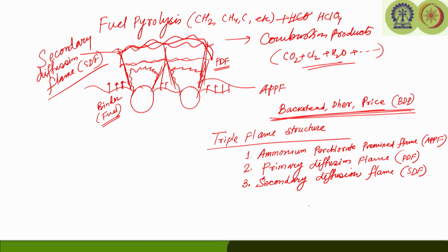Of course, the extent of these different flames will depend very much on pressure, and with increasing pressure the reaction rate will change. However, the diffusion is not going to change much with the increase in pressure, but the reaction rate will definitely increase. So, as the chamber pressure increases, the fuel products find it difficult to reach and mix with the oxidizing species easily.